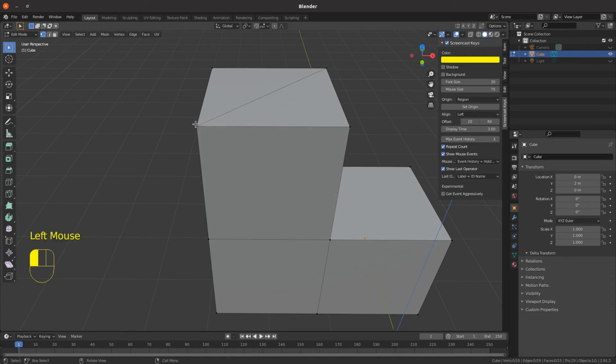And if we select the whole face, you can see even more that the top face is selected, but the overlaying face is highlighted as that there's something wrong. So that's one to look out for, and you need to find out which are the overlying faces and delete one of them.